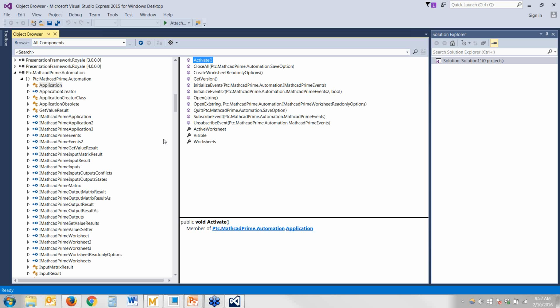So we can send you a link, you download it, and you can integrate Mathcad Prime Express, which is free, to Autodesk Inventor as well. And then likewise, another big example of that is the SolidWorks to Mathcad Prime 3.1 integration as well. That was developed off the API, and now you can link a Mathcad Prime worksheet to your SolidWorks model, and you can run calculations from Mathcad, push the variables into SolidWorks, and likewise read in information from SolidWorks back into Mathcad as well.